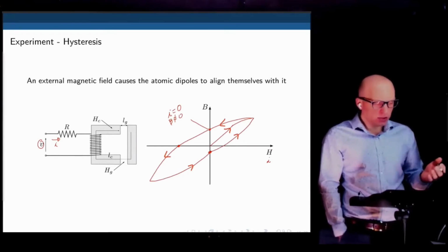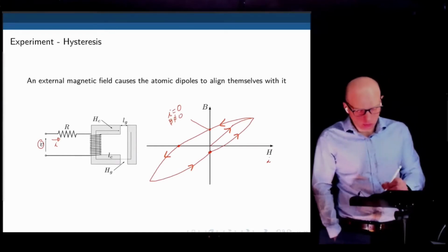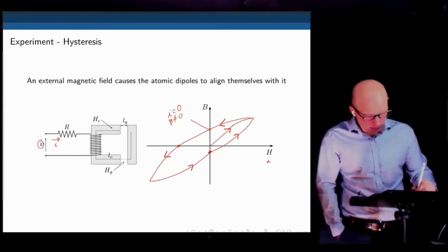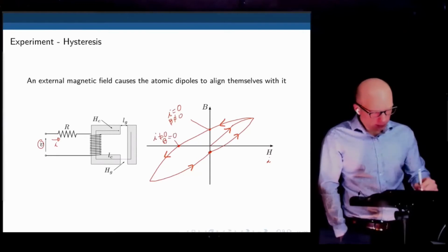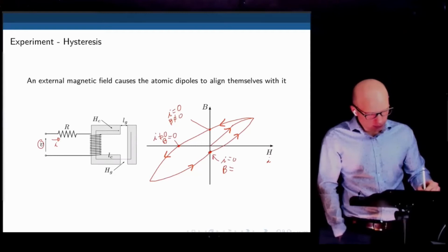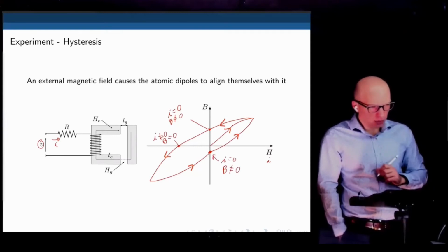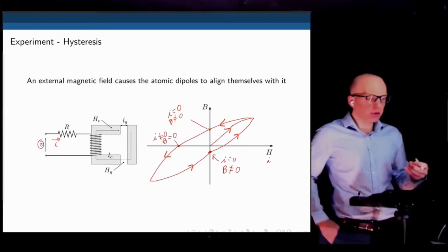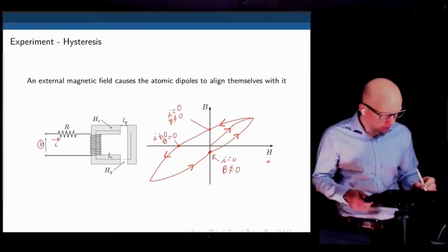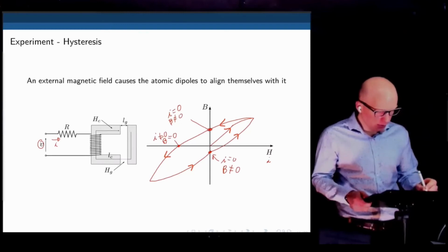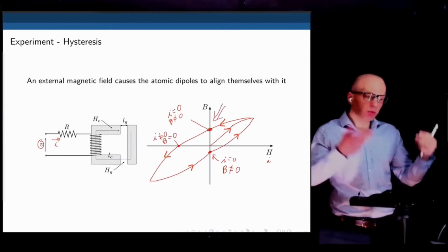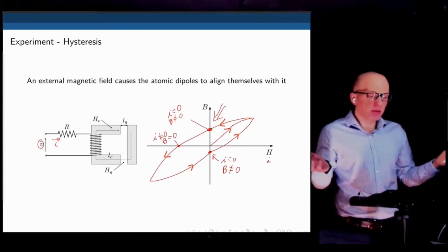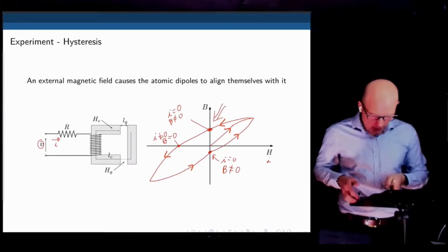And we always have what we call the remnant magnetic field, which poses an important problem, because here current is non-zero, magnetic field is zero. Here again, current is zero, the magnetic field is non-zero. All right, this is a real problem because it makes everything nonlinear. How do we get rid of this remnant magnetic field? Let's say we are at this point there. We apply the current, we remove the current, and the thing remained magnetized. How do we remove that magnetization?